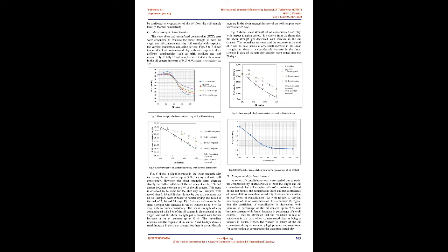The free swell index, FSI, is an indicator of the swell potential character of the soil. The FSI tests were conducted on oil-contaminated clay soil samples with respect to the varying percentage of oil content and at different time periods, such as immediate response after mixing and response at the end of 28 days after mixing. Fig. 4 shows a decrease in the free swell index value with increase in the percentage of oil content.